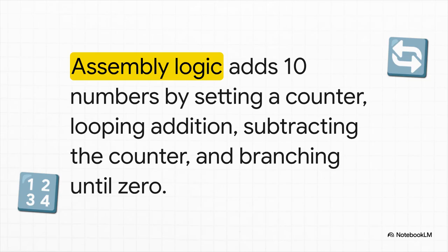on. All right, let's wrap this up by quickly proving you can trace a simple assembly logic loop. This snippet adds the first 10 integers. First, we load the number 10 into register R1 to act as our counter. We clear R0 to 0, that's going to hold our sum. Then the loop kicks off. We add R1 to R0. Next, SUBS subtracts 1 from our counter R1 and crucially updates the status flags. Finally, BNE loop checks the 0 flag. If the counter isn't 0, it branches right back up. It just repeats that cycle until R1 hits 0, leaving our final calculated sum perfectly resting in R0.